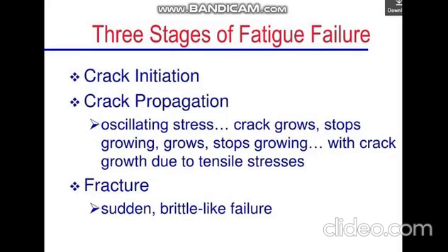Now, talking about the stages of fatigue failure, say there are three stages. Initially, there is something called crack initiation. Initiation means starting of crack. So some crack comes. Why? It can be because of some stress concentration in one place, or some initially pre-existing defect somewhere, or because of the surface roughness or something. Somewhere the crack starts, and then crack propagation.